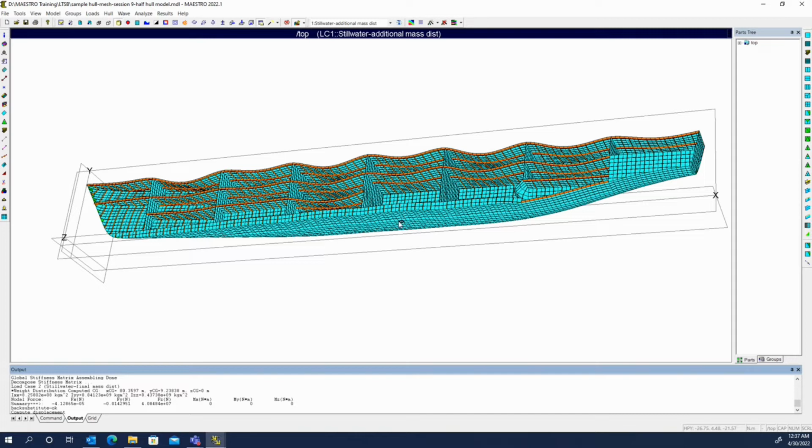So we can see this is basically the hydrostatic pressure on each of these elements. Similarly, we can do stresses, but if we bring up the nodal dialog where we are querying nodes, this is just showing us the location in the vessel, but the nodal query allows us to bring up nodal force, deformation, and then the distance is a utility, so you can measure distances in the model.